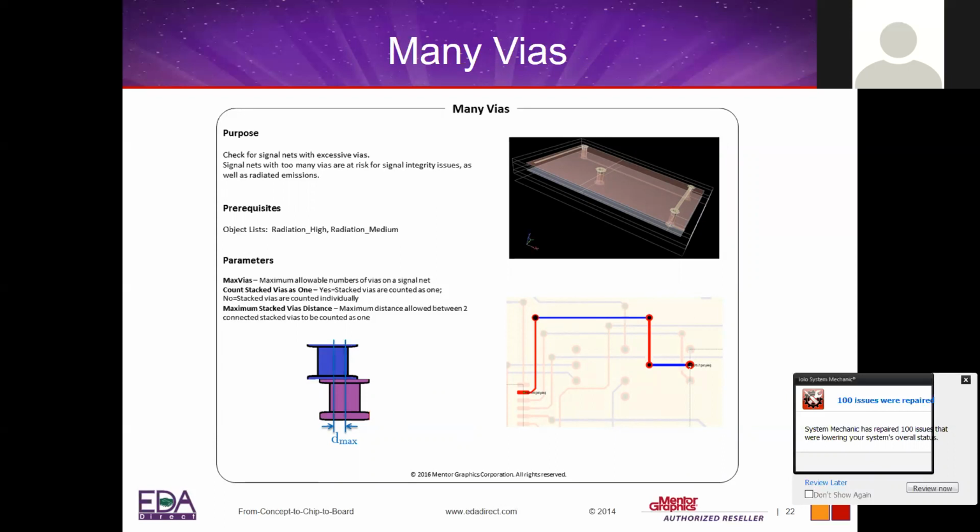You'll be surprised if you go back and check the number of vias on your clock line, your main clock. You will see easily 6, 8, 10 vias on the clock, and that's not good either. Well, why did I do that? Well, the clock has to go to many places. Okay, but did you know the effects of these vias on your clock? Well, I don't know until I go to the bench.